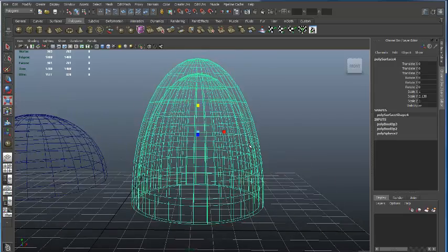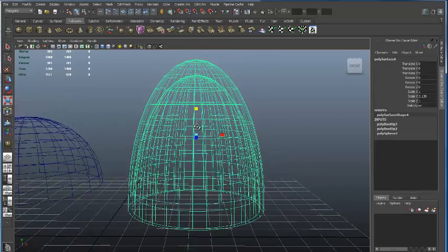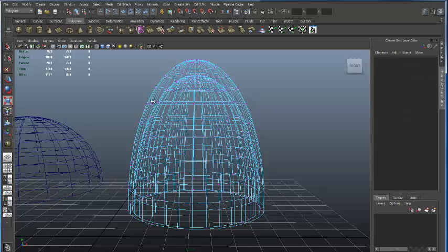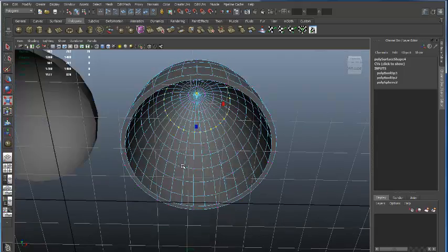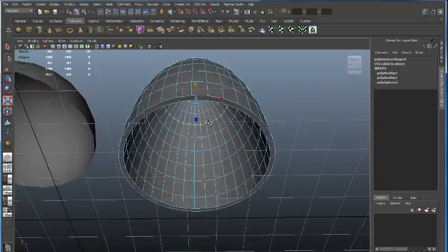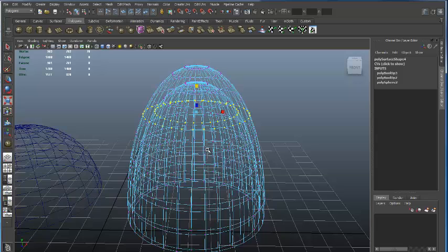Soft select. Okay, the only problem is if you look now, if I go to select vertices in here, you need to make sure that you're also selecting vertices on the inside. Okay, because there's inside topology happening in there from the Boolean that I did. That makes sense, right? So if I did soft select, I wouldn't just be selecting the outer ring, which I could. Remember, I showed you how to do that.